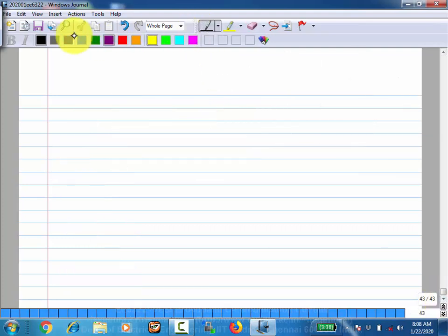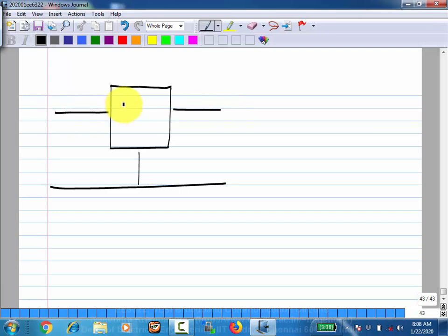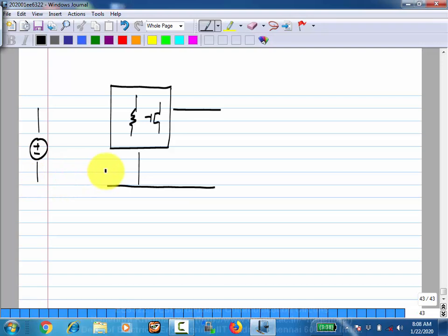So a couple of things. Firstly, I won't go into details, but let's say you have any two-port with a number of noisy components inside, resistors, MOS transistors, and so on. And you can drive it with any kind of source, by which I mean a source with any impedance. And you want an input referred noise representation for this situation, which will work for any kind of source. Now it turns out, I won't go into the proof of this, it can be proved from elementary network theory. Essentially, you calculate noise transfer functions from here to the output and then divide by the transfer function square.